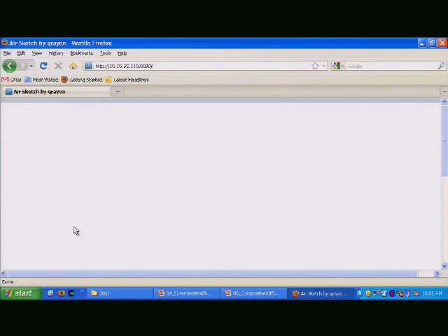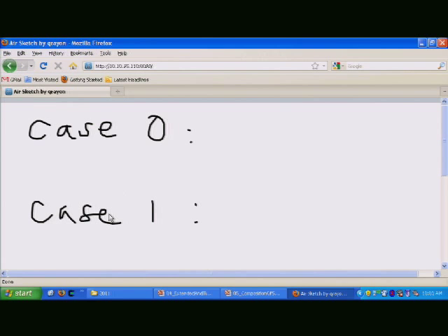Okay, there we go. All right, so when you code in C, you will code up a state machine as a switch statement, and every state will be a case in the switch statement. But it's not really an entire state of the state machine because you'll have other things going on. So let's say you have another variable x, which in this state you assign to y plus z, for instance. The value of x and the value of y and the value of z are also part of the state, right? So the entire state of your machine has to comprise not only the value of this variable that you're switching on, but also the value of every other variable in your program.